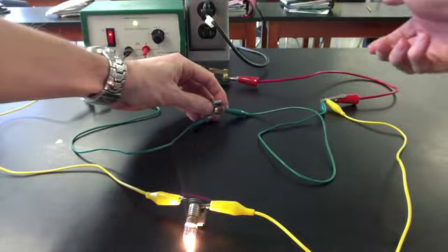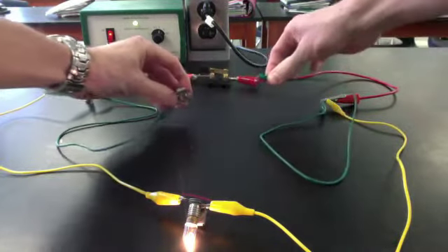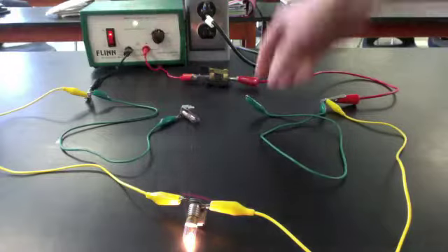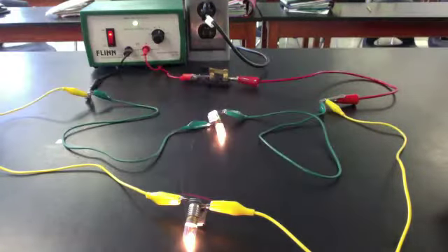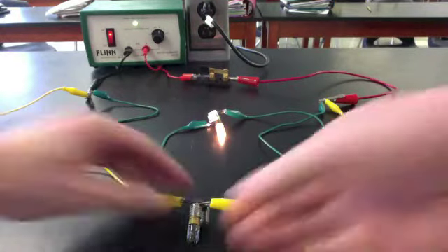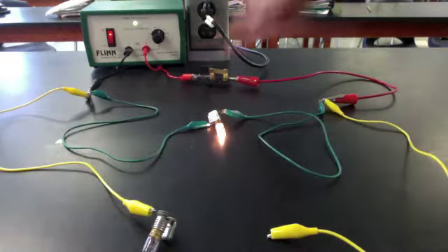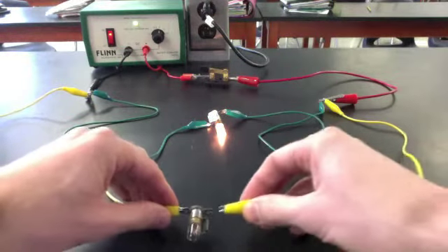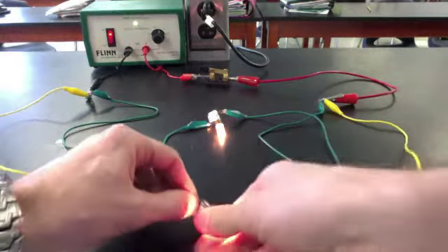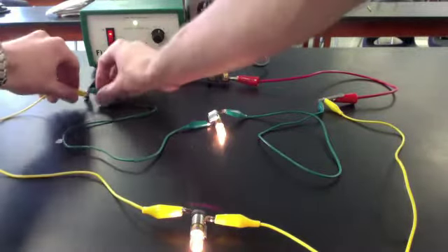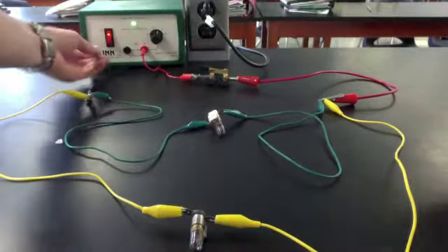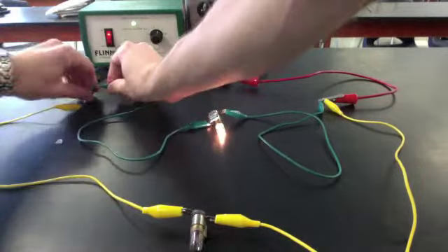If the bulb goes out, or a wire is disconnected on the green path, the yellow path stays on because it still has a complete path. Same thing with the yellow. Bulb goes out, or wire is disconnected, the green path still works because there's still a path back to the power supply. If a wire is disconnected after they return back together, then nothing works. There's no complete path.